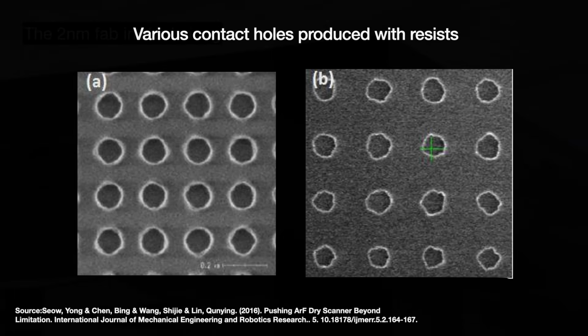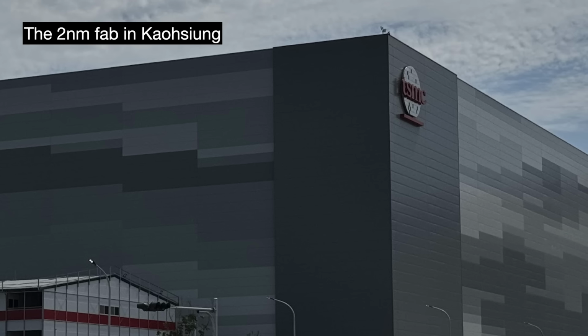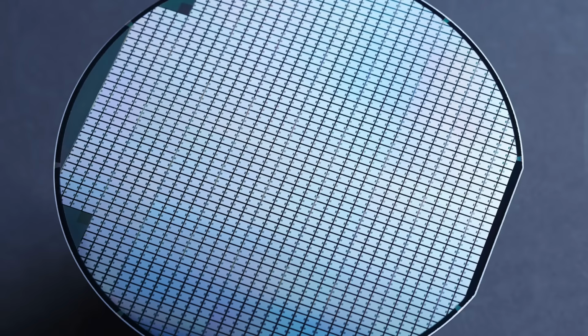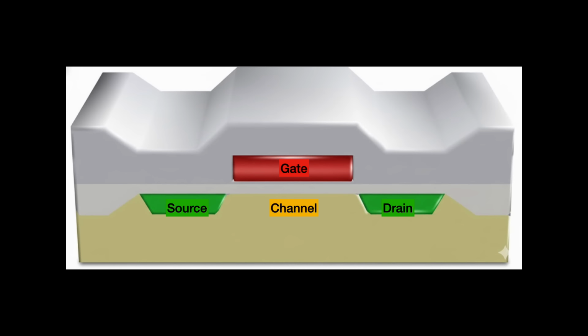The process node's ultimate goal is to fabricate these very small devices at high volume. The devices must be consistently sized and perform reliably over a long period of time. Deviations can cause the device to perform below par. We can measure this via a metric called parametric yield, or the device can outright fail, and that's measured using catastrophic yield. Here, I want to note that people have spent their whole careers studying each of these steps. I'm not going to go into these steps with intense depth. The goal is to keep moving forward, so variations abound.